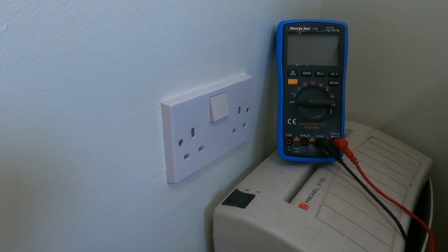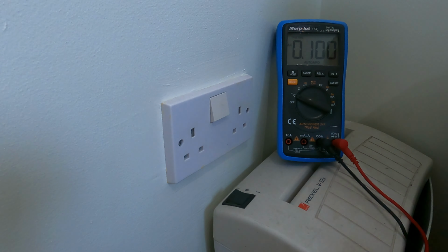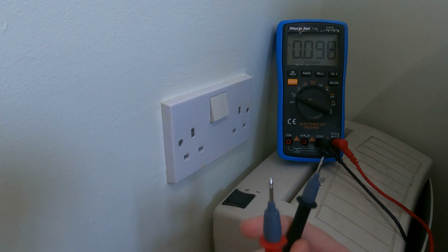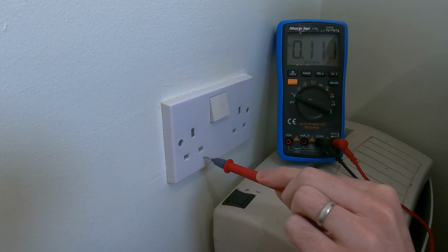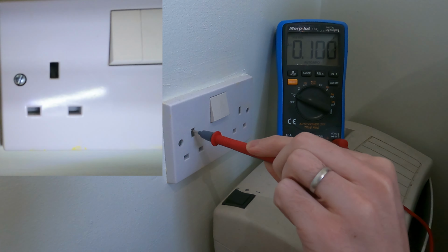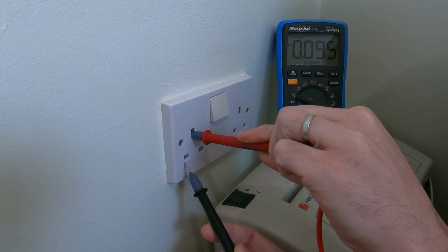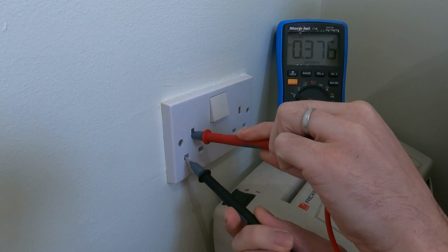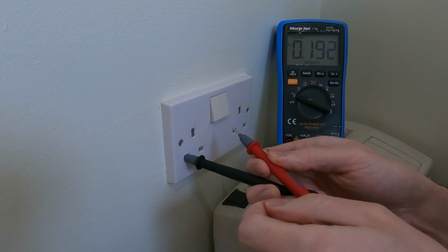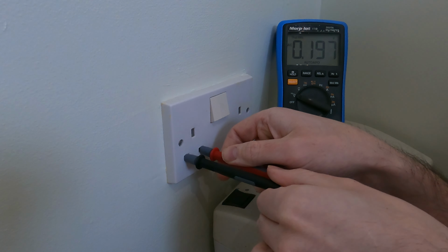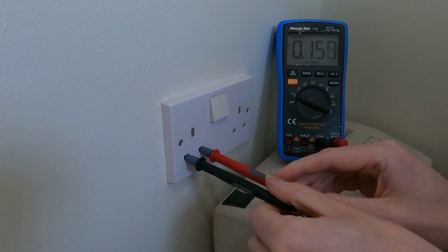Okay. Once you've done your safety checks, you can then go ahead and twist your dial over to the voltage symbol with the AC sign. We then get our red test lead, and what we need to do is release the safety guard on the bottom 2 holes. The way in which we do that is you get your test lead and you pull it down like so, and that will release the guard at the bottom. You can then go ahead and put your black test lead in the bottom left like so, and then you get your red test lead and you pop your red test lead in the bottom right, like that. Make sure you always put your black lead in first, followed by the red lead.